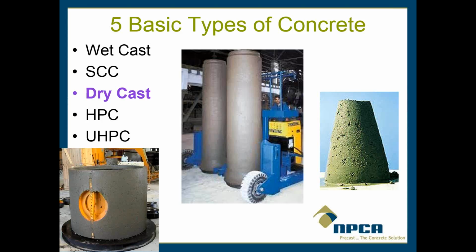It is made with mechanized equipment instead of your traditional method of pouring or casting. It's unique in that it can be stripped immediately after casting and consolidation, so it helps you with mass production of pipes or manholes and stuff like that.